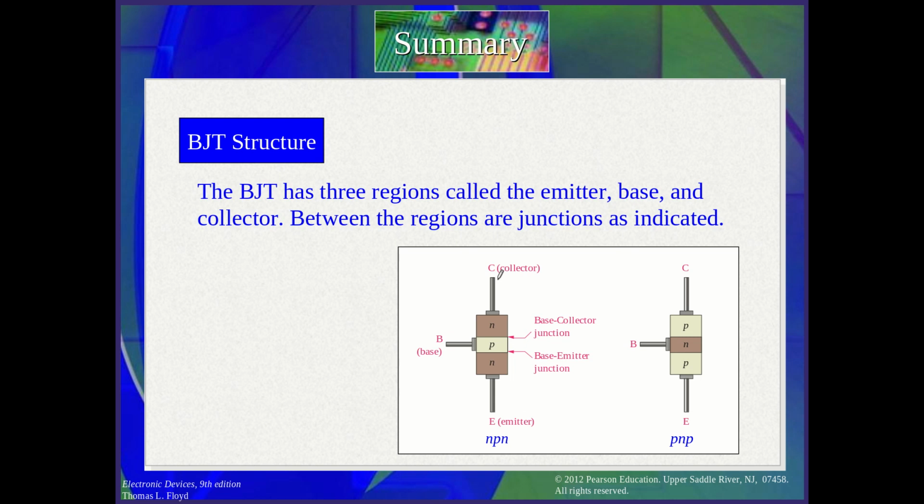There is the current transfer ratio, or CTR, which measures the efficiency, how much the output compares to the input, which is typically from 50 to 110% for standard optocouplers.